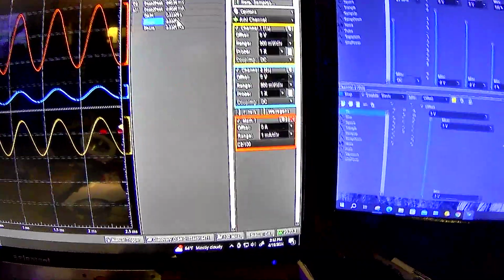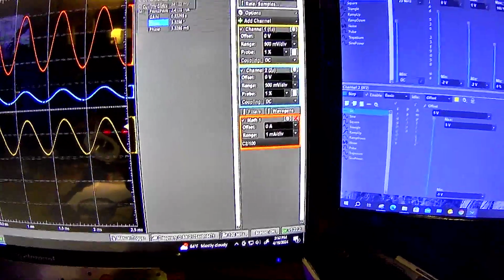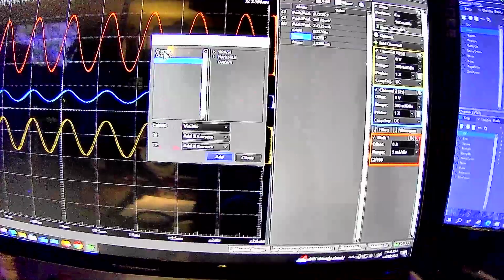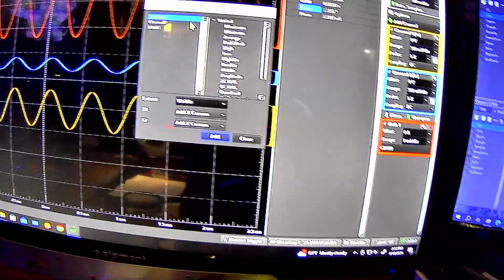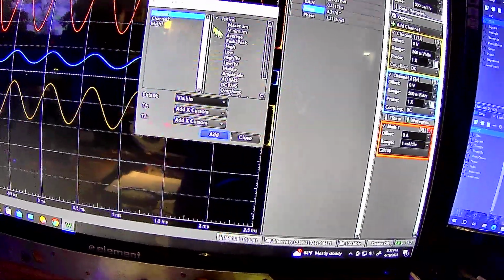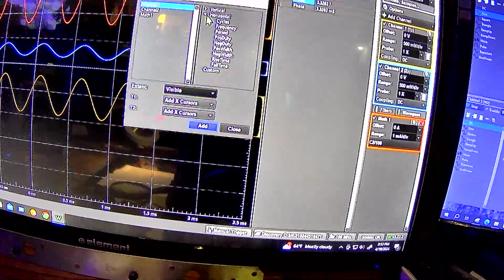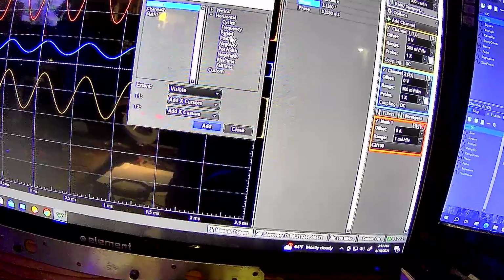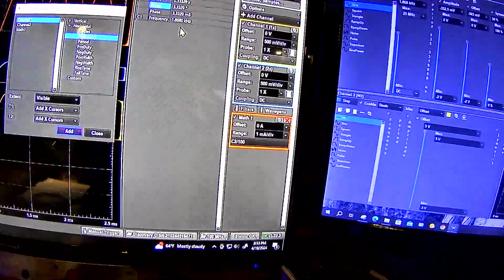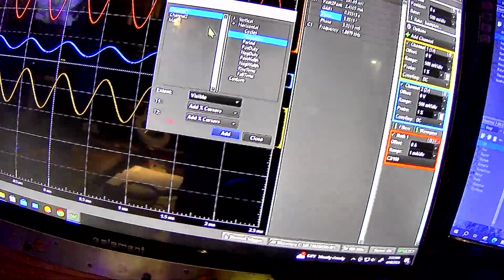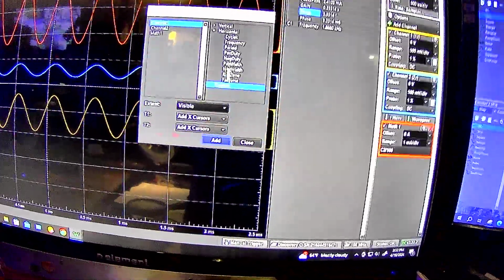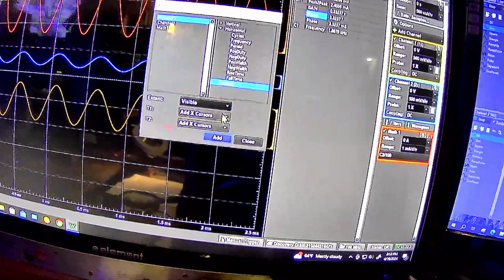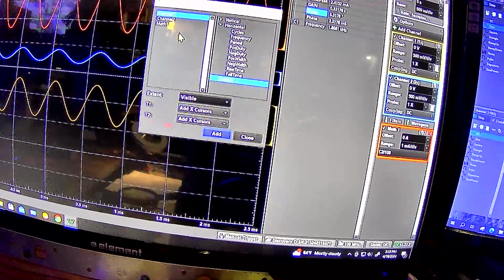I'm interested to try that out when I get an actual voltage amplifier. This is a built-in default function, because to add a measurement, they have defined measurements, but you have to pick them for every channel. For a given channel, they've got a bunch of vertical and horizontal measurements. I could add, for example, frequency, and you see frequency pops up there. You can do custom, but the problem with custom is you're limited to that very channel. It won't let you work outside of that scope.